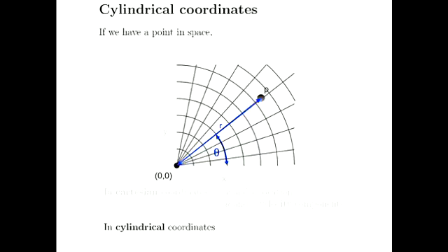So we define that point P in terms of radial position r and an angle theta. We also have to define two new velocity components: the radial component of velocity, which I'm calling u sub r, and the azimuthal component of velocity, u theta. Is it making sense? All I want to do is convert that set of equations from Cartesian to this new coordinate system.